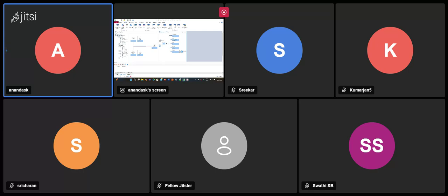And then we have trace. In trace, you can see all the CAN messages like Tx and Rx messages. And as Kumar mentioned, in the graphics you can see the actual waveform of the particular signal, in the form of zeros and ones, so that you can see in this graphic. And logging already we discussed.